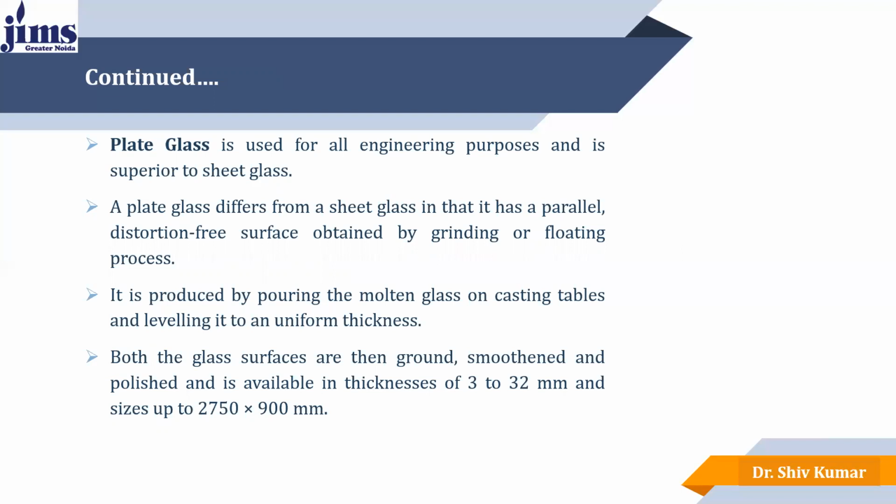thickness. Both the glass surfaces are then ground, smoothened, and polished and is available in various thicknesses starting from 3 mm to 32 mm and sizes up to 2750 by 900 mm in length and width.